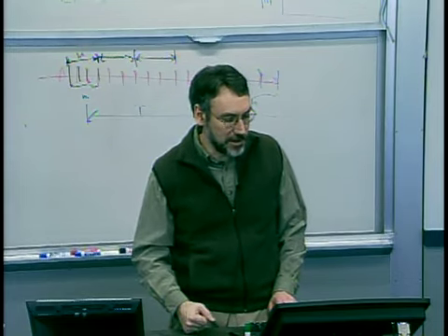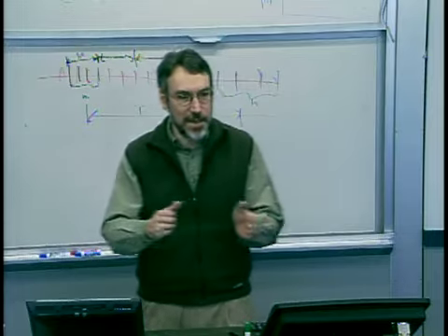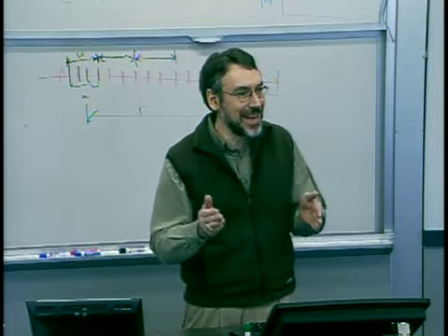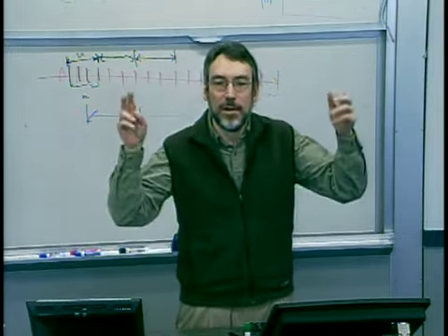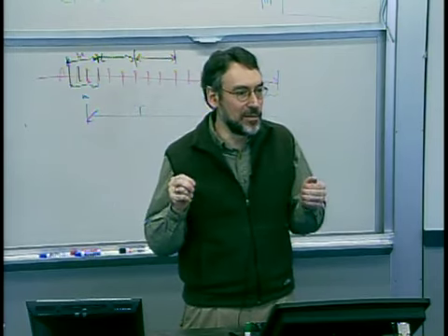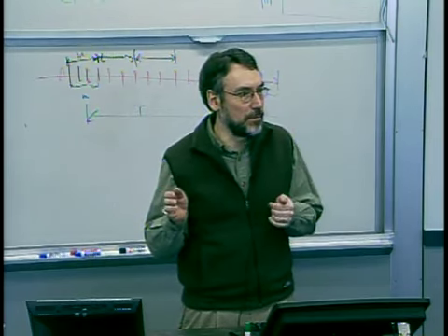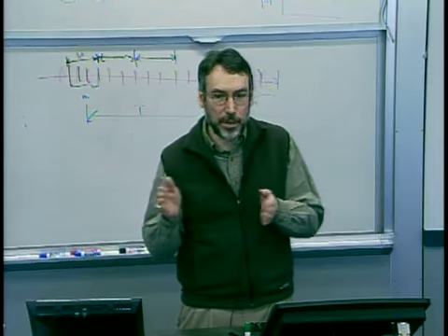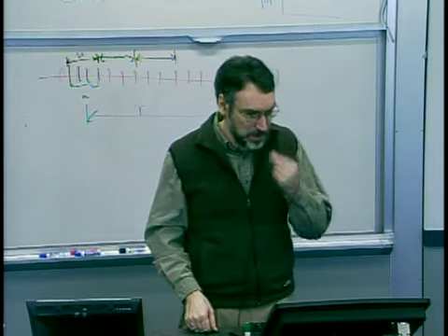And here's one last example. In this case, now I've recentered, got my CPK up to my full theoretical possible CP of 2 by putting it back on the target, putting my mean back on the target.